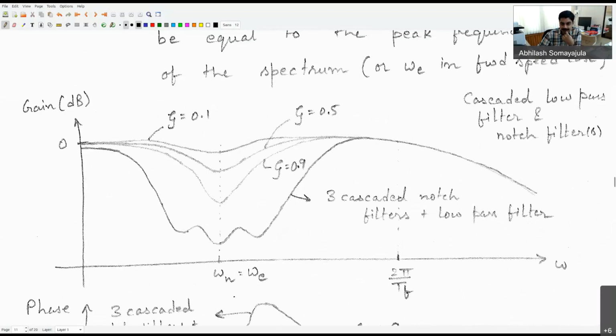So let's see what happens. When we have this zeta value specified as 0.1, so the damping is low, then you will see that this thing is barely making a dent here. Correct? Now, as I keep increasing zeta, you will see that the effect of this filter is that in a particular band around the frequency of interest to us, it's reducing the gain value.